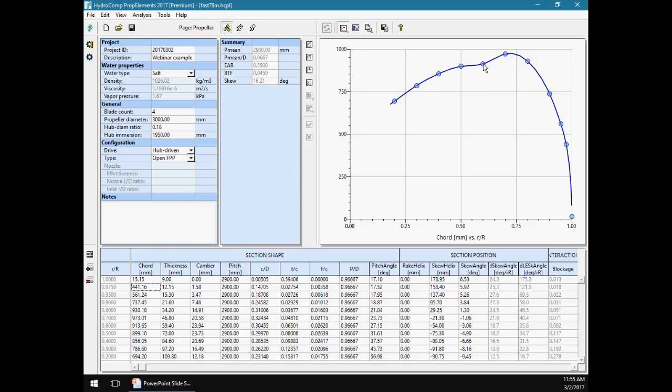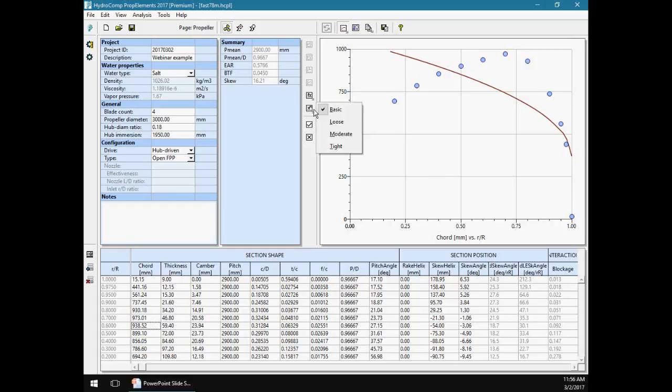So what I'm going to do is first take this 0.6 and fit that point. So I'm going to go down to my 0.6 column here, and I'm going to fit this point. So I'll accept that fairing. It's still not great. It's a little bit better. So I'm going to use a mathematical fairing on this. We have a couple different spline types or algorithm types. One is a normal, but because our chord length goes to 0 at the tip, I'm going to use a tip weighted, and I'm going to loop through different levels. That's not bad. I can get a little bit closer, or I can do a very tight smoothing.